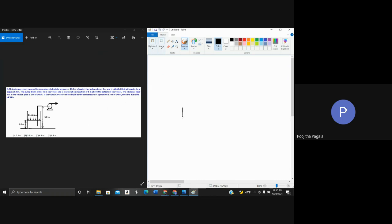So we have a tank which is filled up to 2 meters with water, and the atmospheric pressure PA is 10.3 meters. So what does this mean? This means the pressure at any point is equal to the pressure of a column of water having a height of 10.3 meters.